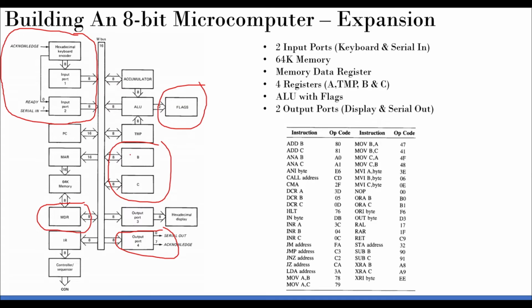So definitely this is much improved hardware compared to our simple 8-bit microcomputer. And in addition to that, if you see the bit size, the program counter is now 16-bit compared to our 4-bit actually. The reason is very simple, because your memory is 64K. So what does 64K mean? Okay, very important to understand that, right?